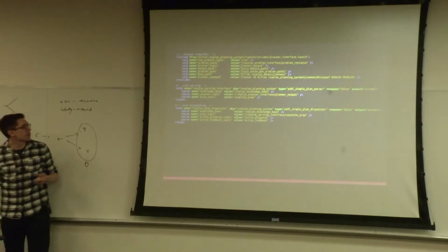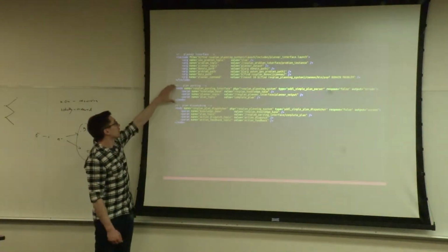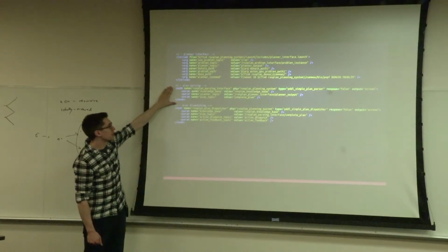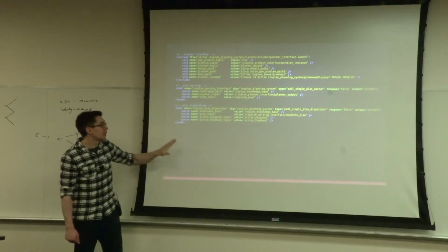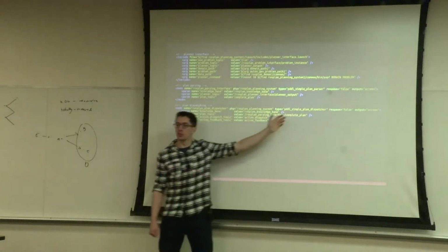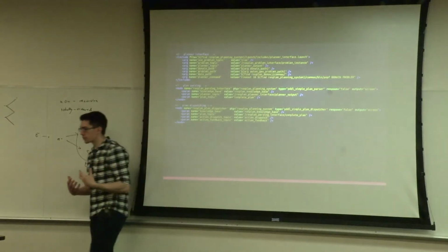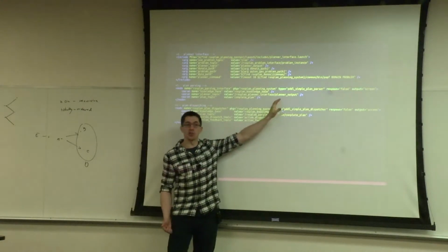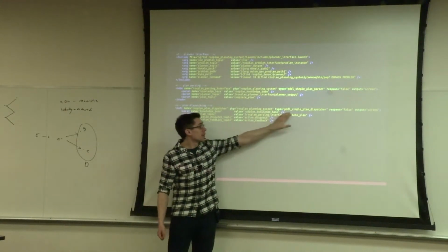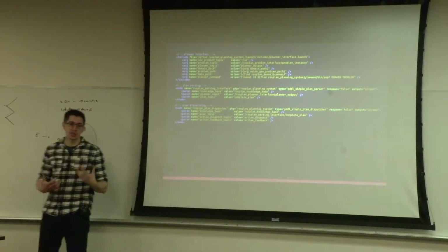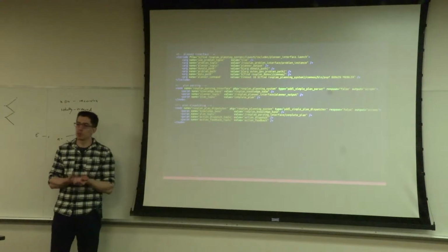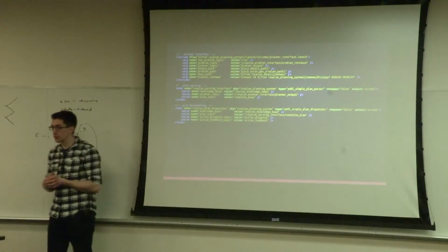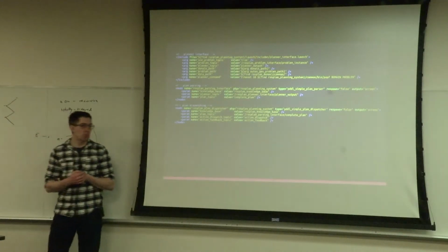So here is a new launch file which adds two more nodes. The ones above are the same as before. We're adding this plan parsing node and this plan dispatching node. And there are multiple executables which implement this interface. We're using the simple plan parser, which is going to create an array of ROS messages, each message being an action, and the simple plan dispatcher, which is about the simplest plan execution algorithm you can get. It will publish the first message in that array, wait for it to say that the action was successful, and then publish the next message. There's no concurrency and no other checking.